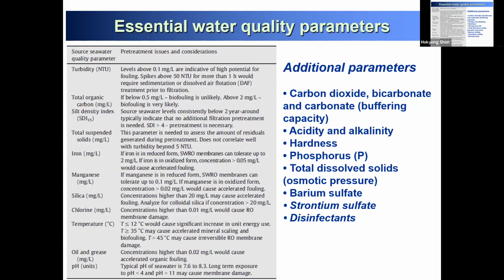So the membrane, we just say reverse osmosis can make this. If you have a higher concentration of total dissolved solids, osmotic pressure is higher, then you need more pressure to separate your water molecules and sodium or other salt. That's the reason why seawater desalination is very, very energy intensive, because pressure has to be 60 or 70 bar.